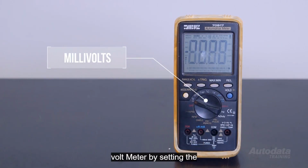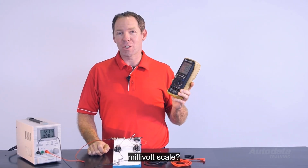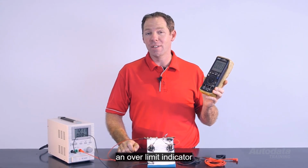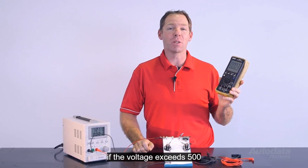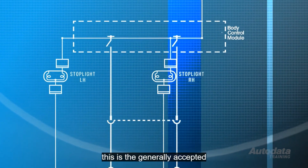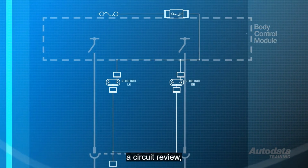Prepare the voltmeter by setting the scale to millivolts. We use a millivolt scale because most digital meters display an over limit indicator if the voltage exceeds 500 millivolts, or half a volt. This is the generally accepted maximum allowable voltage drop for a circuit.